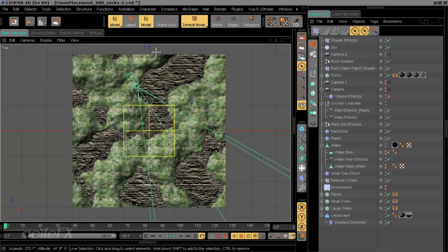So what we want to do is create a texture for the terrain, basically just using the UV, and have one tile over the entire terrain, black and white, basically an alpha that's going to cut everything out that we don't need. So you can either create a new texture and use body paint to paint in where you want the objects left.